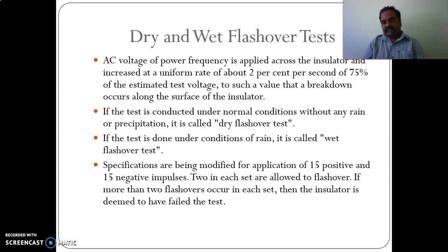As we have already seen, the power frequency tests are of two types. One is a flashover test, the other one is a withstand test. Now we will see the first one, flashover tests, which means that for your insulator, you are supposed to identify the voltage at which your insulator will experience a flashover, and also the maximum voltage which your insulator can withstand.